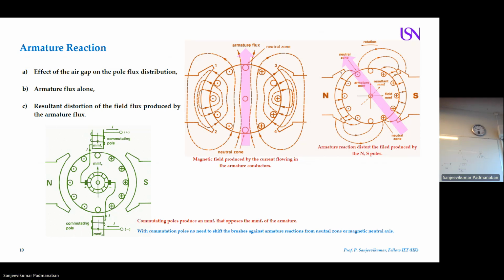Second option: I know the armature reaction current and voltage parameters. I measure them using external equipment, a voltmeter and an ammeter. Then I design another small inductor coil and apply a small voltage to it. It will generate a current and voltage opposite to my armature reaction current and voltage. So when I add them, they neutralize, and the resultant becomes zero. This coil is called a compensating coil. So in a DC machine, we also use compensating coils in order to control armature reaction.